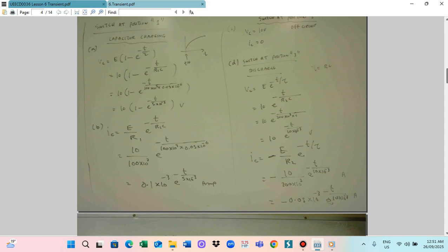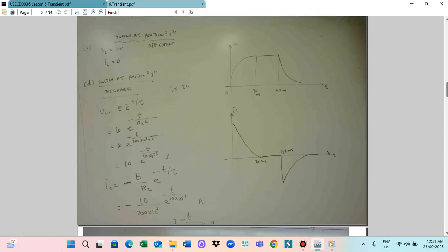And the voltage across the resistor is E multiplied by e power minus t by RC. So those are for the resistor and capacitor series circuit during charging. During charging, the voltage grows, the current decays, and they can be calculated by those formulas. Okay, this first one we already talked about, the charging.